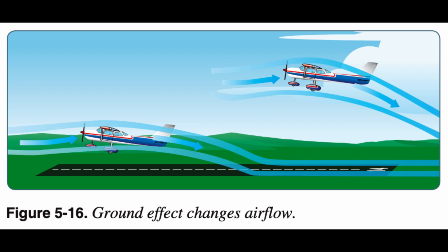Ground effect, then, is due to the interference of the ground, or water, surface with the airflow patterns about the aircraft in flight. While the aerodynamic characteristics of the tail surfaces and the fuselage are altered by ground effect, the principal effects due to proximity of the ground are the changes in the aerodynamic characteristics of the wing. As the wing encounters ground effect and is maintained at a constant AOA, there is consequent reduction in the upwash,